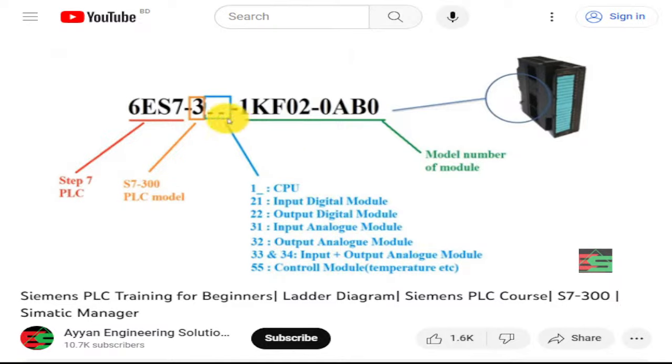Okay, and go to your Simatic 300 station. This is your PLC. This 2 digit will show the module type. And last one is the model number of the module. So a very important thing is in these 2 digits. By these 2 digits you can know the module type.